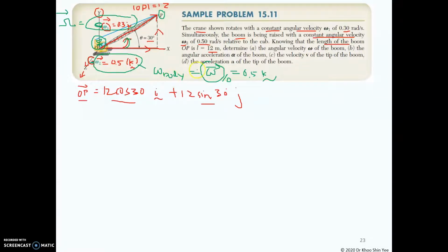Make sure you know how to differentiate which one is the angular velocity for the body and which one is the angular velocity for the frame, and use the corresponding symbol to indicate the difference between them. And normally we use the symbol r to indicate the displacement vector. So since you are pointing from O to P, we write r P with respect to O.